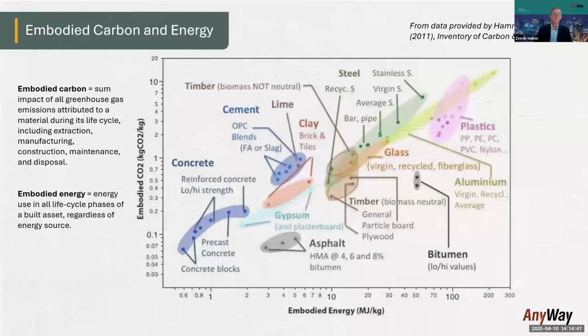Sure, thank you. It's a well-circulated diagram. It's about 15 years old, and we can talk about the actual accuracy of the embodied CO2 and embodied energy. But at the end of the day, what this diagram is trying to show you is the impact of our industrial processes or materials that we're using on the environment. If you look at concrete, and we're talking about how impactful that is on our environment, yet it's quite low on this graph, what we need to remember is that's the concrete component.